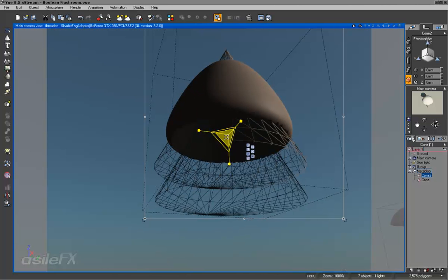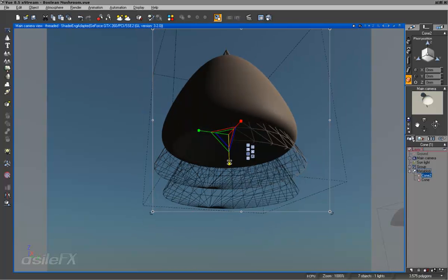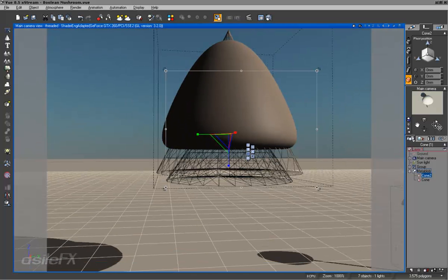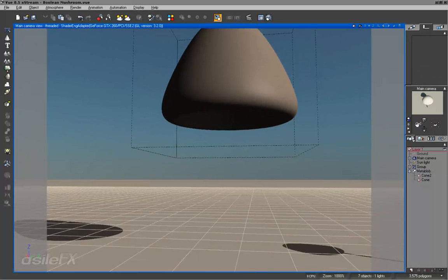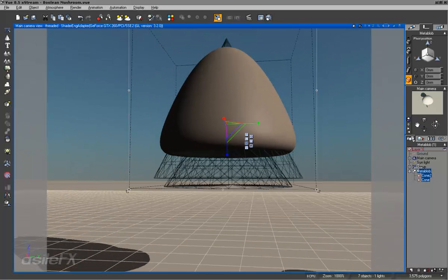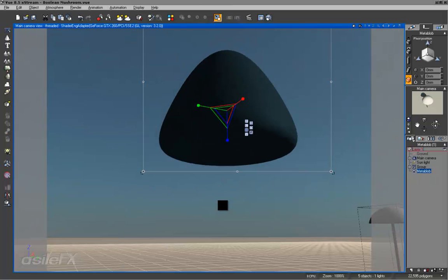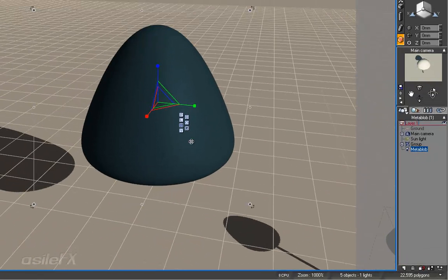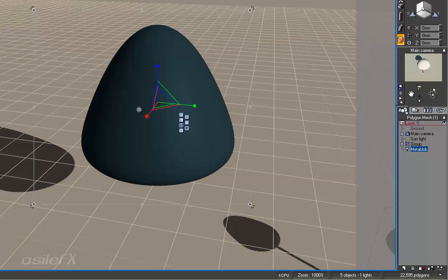And then we can just adjust the shape in order to really get what we're looking for. So that actually looks better than the setup I had before. It's a much taller looking mushroom. And then what we would do is bake this to polygons. So select the Metablob, right-click, bake to polygons, set it to a higher mesh value. This one ended up being, I think, a higher resolution than the other object. Double-click and take a look and see that we do have 20,000 polygons, which I don't think we need that many. View handles polygons very well, but even still.